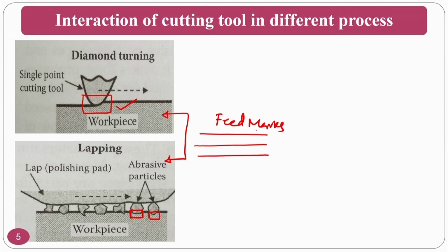Okay. So, that is a drawback. At the same time, if you see here in the lapping process also, the lapping process is a 3-dimensional or 3-body abrasion that takes place, wherein you will have random surface roughness marks. So, this is another disadvantage because of this feed mark, the vision systems that are used in optics may be destroyed.